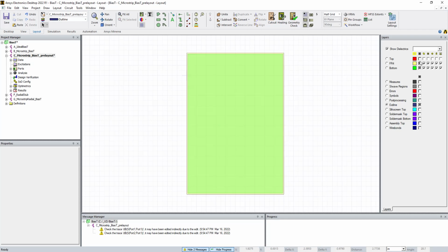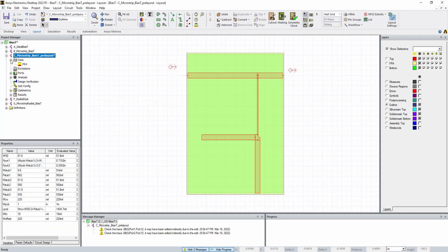Alrighty, so we're pretty close to being at the end. I know this is insanely painful, but bear with me. So I think we have defined all of the layers. And so we're just going to go through, and I think that's going to be pretty much it for this last session. So we have our layers, they're all defined, solder mask top and bottom. We're not going to do the silk screen yet. We'll do that in the next video. These are all defined, that's great.